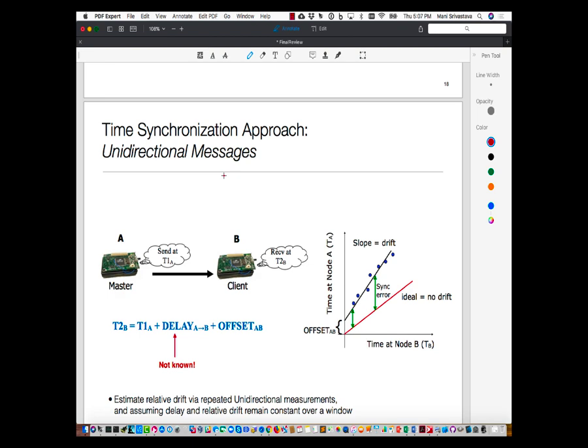The problem there though is that the delay from me to you is some unknown thing. So in reality, your clock will always be that delay behind, but this is acceptable if the delay is pretty tiny. Usually that would mean short range. For example, from my radio to a nearby radio, you're probably looking at on the order of 10 nanoseconds or so.